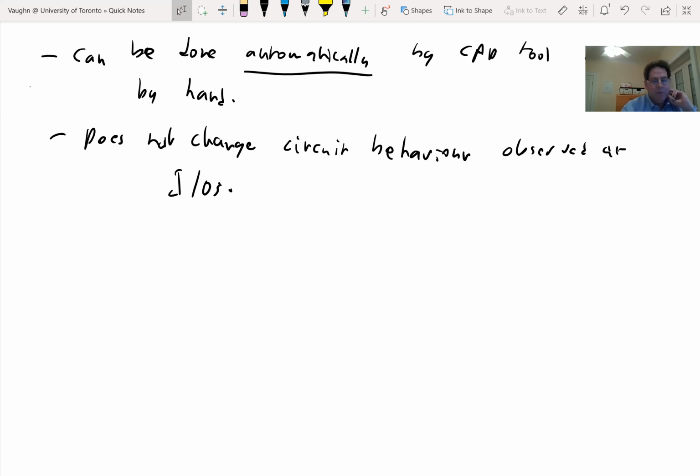So compile time. So it's true. It's a complicated optimization, so it can increase your compile time. So if you don't need it, that's a good reason not to do it. Retiming, it's hard to tell how your stuff affects your circuit timing. So I guess you're saying it would be difficult to tell if you're writing your RTL in a way that was more or less timing friendly.